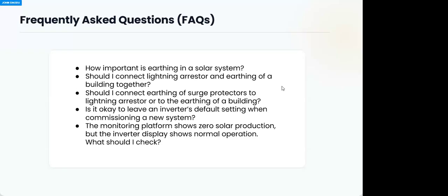Then for the voltage, the manufacturer said the bulk voltage is such a value. Okay, charge controller, I will program you to this value so that when the batteries are fully charged, this is the value they get to, and they will not be overcharged. I think that answers that question.